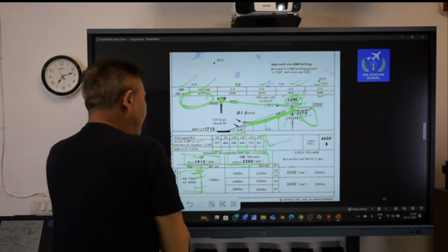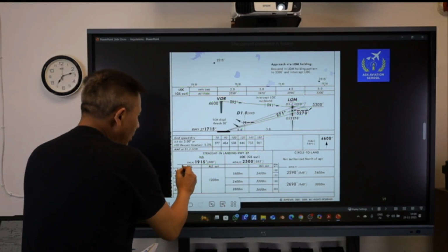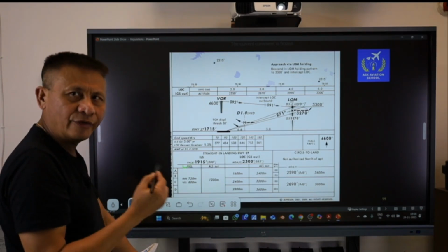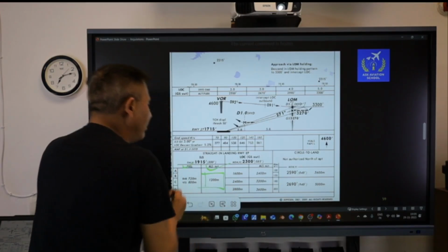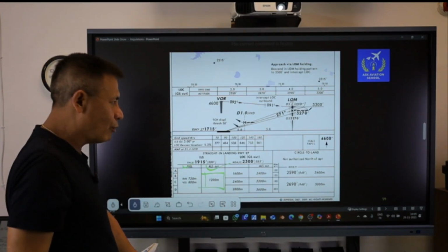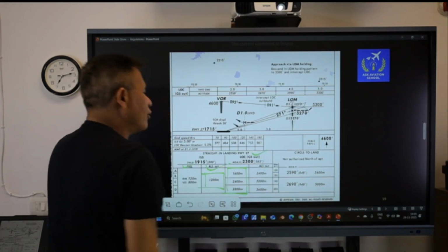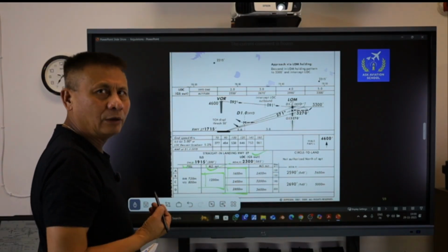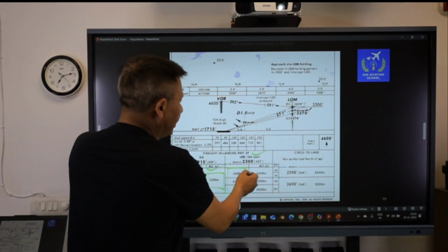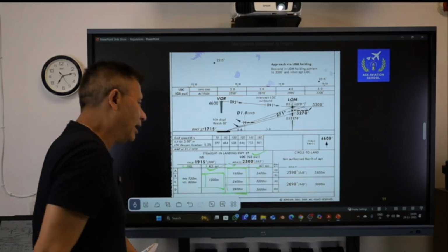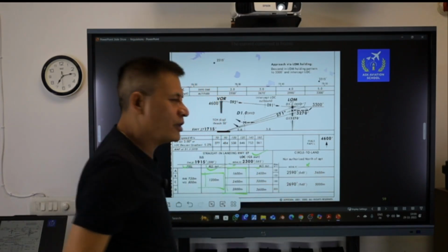Similarly, for this particular figure which is given, it is whenever the full approach lighting system is in service. When the approach lighting system is out, the RVR minima has now increased to 1200. The similar figure is written here. This is in case of a glide slope out, that is if you are carrying out an only localizer approach, then thereafter the visibility criteria with full ALS and without ALS is given in this. I will not be explaining this part, the circle to land.